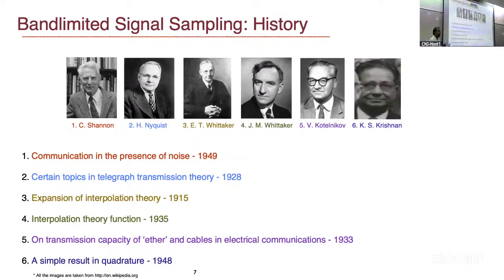Is the sampling good enough? So can we do all the digital processing after sampling, or should we do something more? Quantization. Why should we do quantization? All those samples that I showed still have high precision. What do I mean by high precision? They can take any values, right? Of course, I cannot store them in terms of bits or finite things, right? So I need to do some sort of quantization.